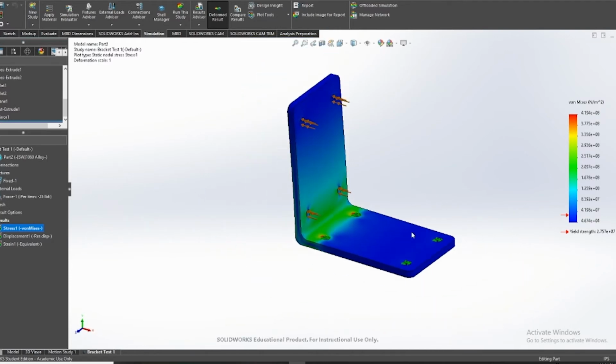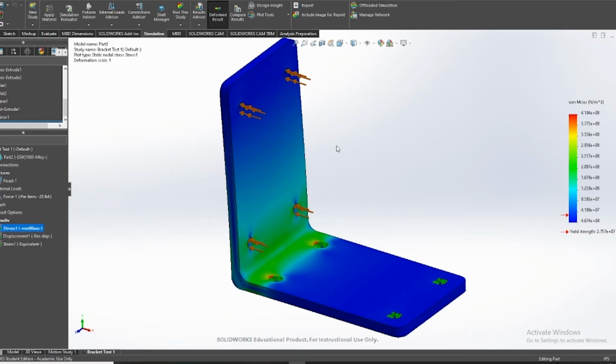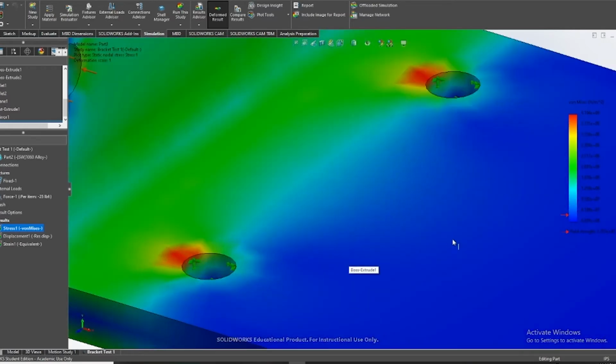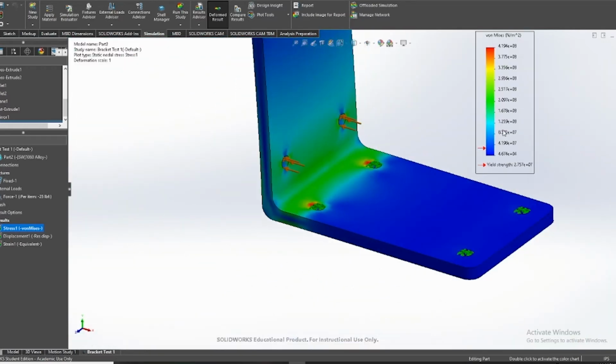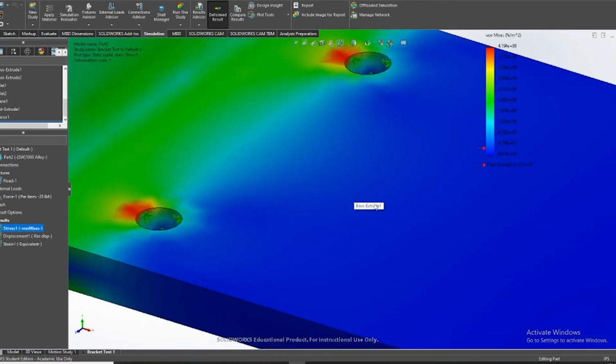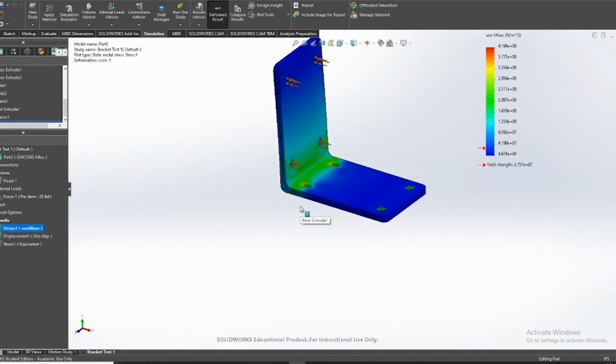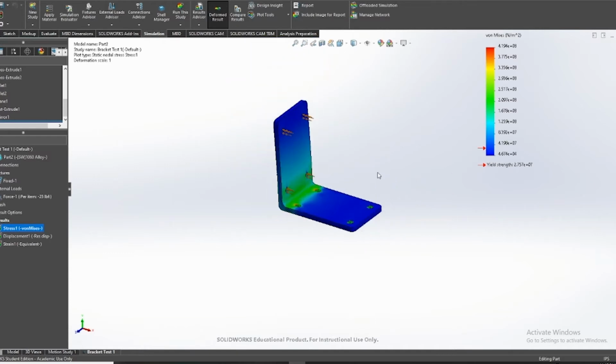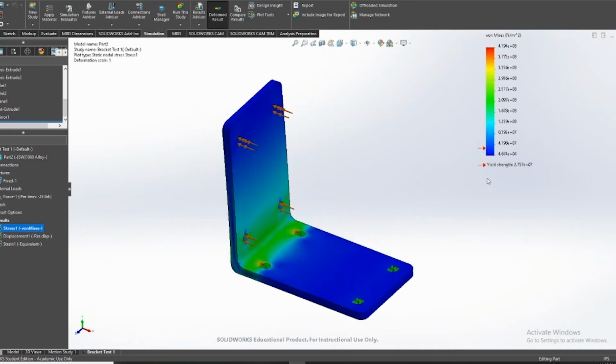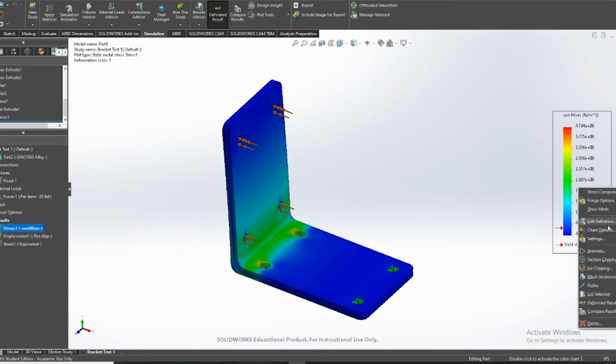So you might be wondering how you would figure out which parts are actually under all that load. You can't really tell what blue is what. Where in here does it stop being under the yield strength and start being above the yield strength, so I know where I need to improve this part, or where I need to, say, add a rib. There's a good way to do that, and it's really great. SolidWorks does a really good job of this part that not a lot of CAD softwares do.